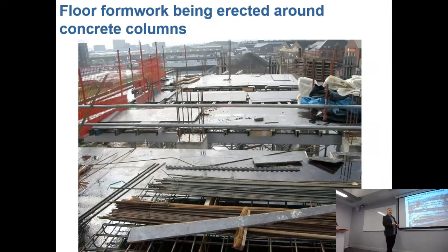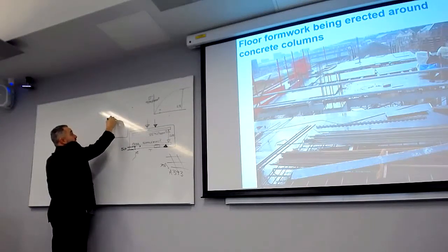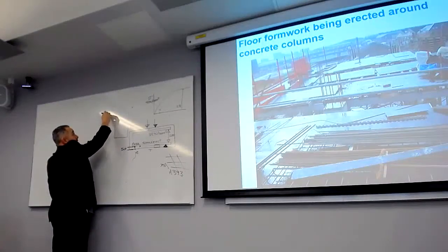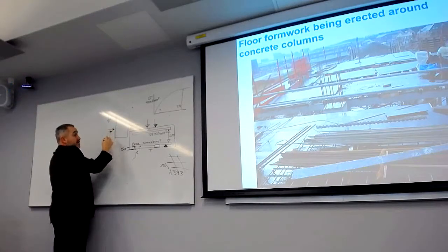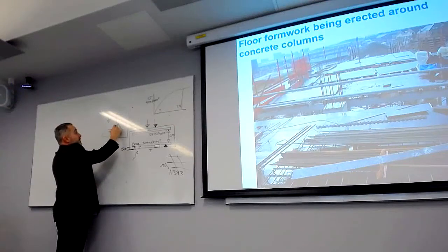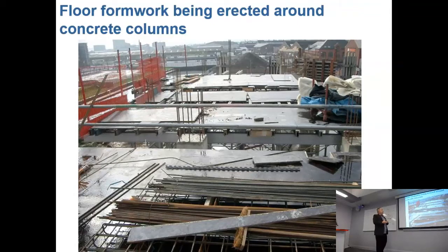The contractors design the formwork. We don't do that in this module, but it's a bit like an excavation, where the concrete weight gets transferred. If this was concrete being poured, you've got the water and the load pressing against this formwork, and you've got to make sure the formwork is strong enough to hold everything back, and that any falsework is fine to keep the concrete back.